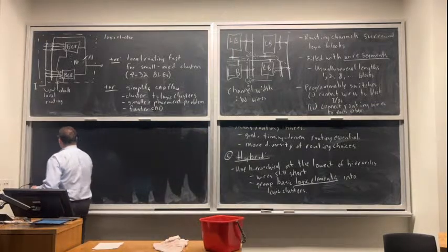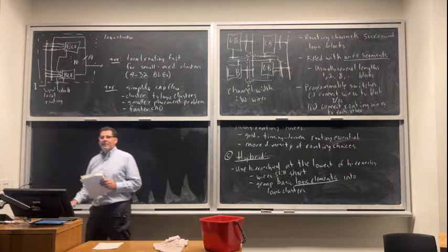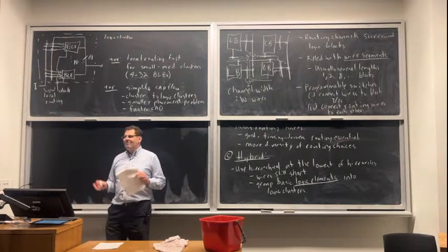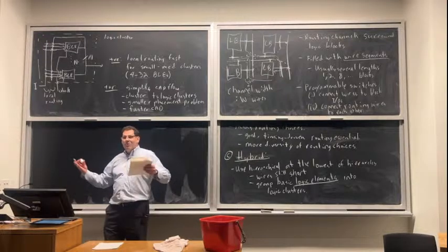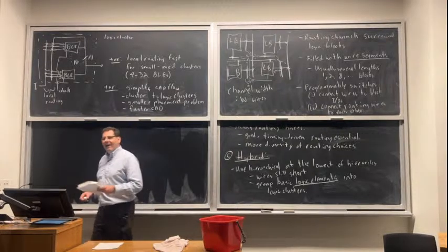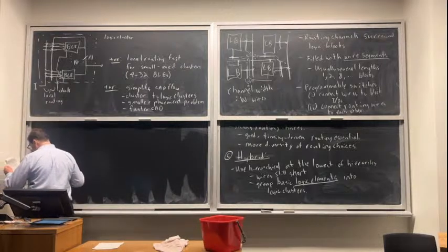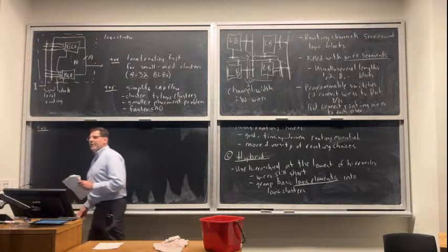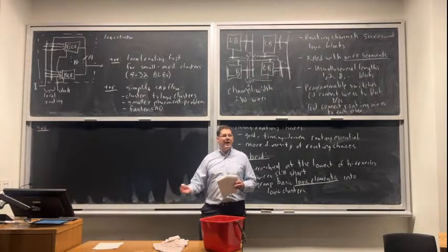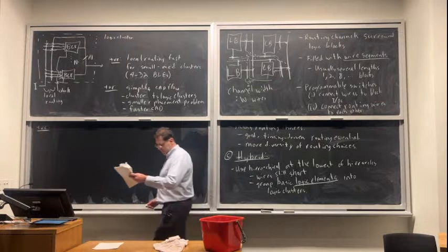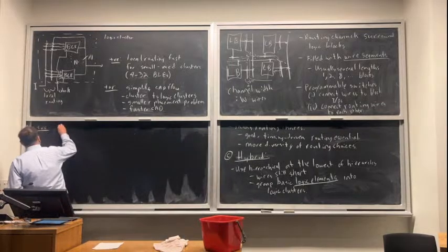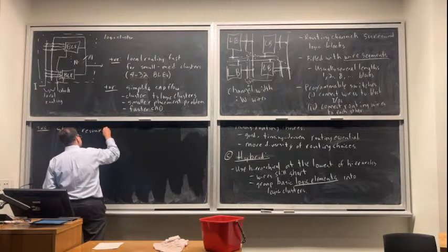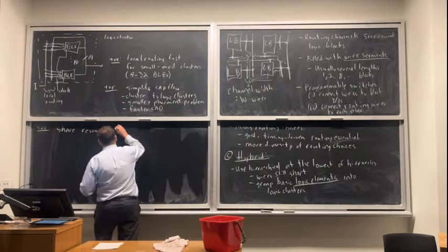Okay, so another positive. What about this clock? Does this seem like a good thing, that I can take the clock and just hook it up to all the BLEs in there? Seem logical? I guess I told you it's logical, right? So that's another advantage. This gives us a natural way to support word-wide or shared signals. Clock is maybe the most obvious one. So we can share resources that don't need that much flexibility.